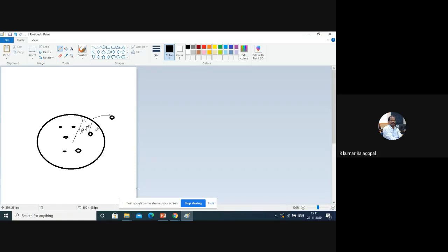Even Chipcon or Nordic will support 100 meters. Other devices will not support it without noise. So even industry people will select Chipcon devices for transmission without noise. So if this device is out, automatically it will be discarded from the network. Suppose once again the device comes in, then automatically it will be considered and assigned the hardware address and also the PAN ID. That's a common PAN ID only; the individual node address will be different. That's what is available.